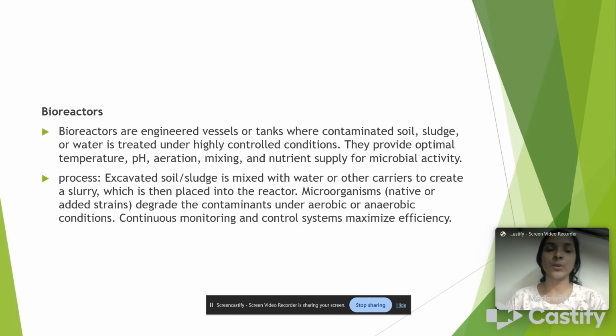The collected soil or sludge is mixed with water or other carriers to create a slurry, which is then placed into the reactor. The microorganisms degrade the contaminants under anaerobic or aerobic conditions. Continuous monitoring and control systems maximize efficiency and enhance the degradation process.